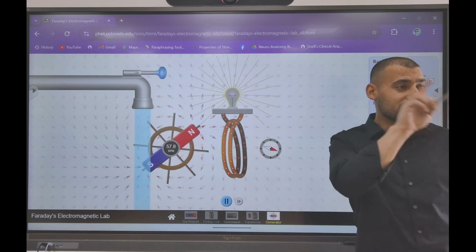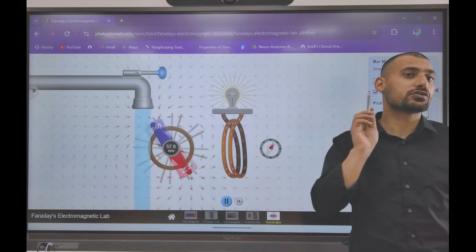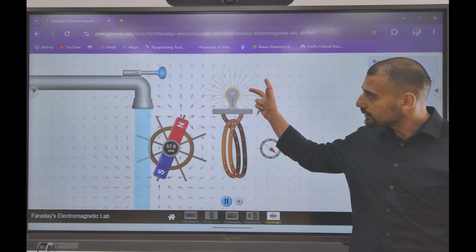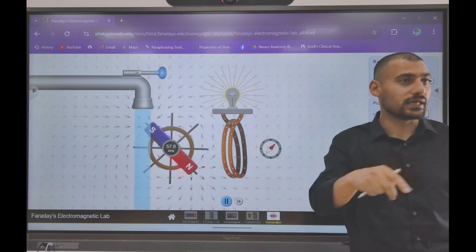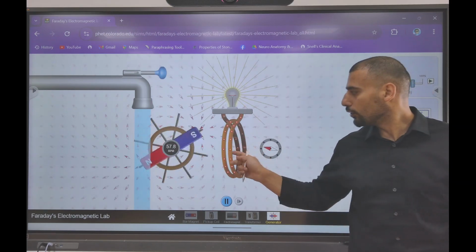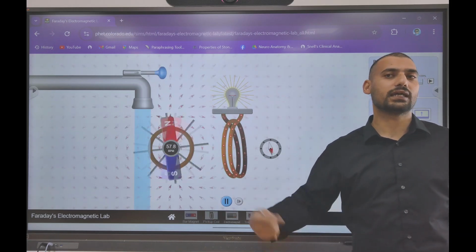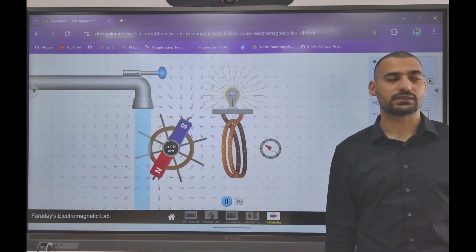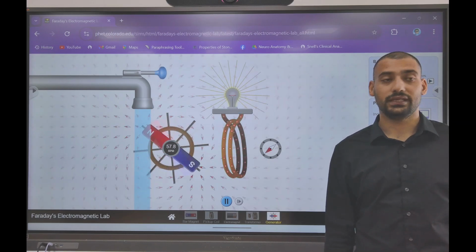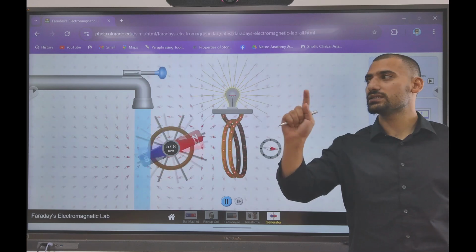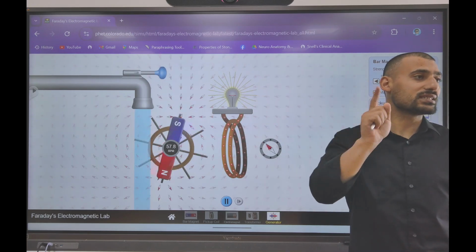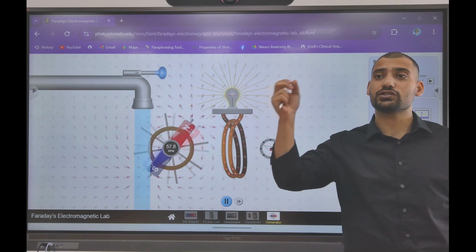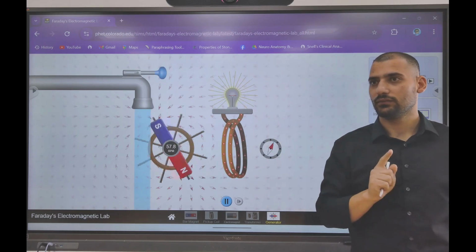And remember, in one cycle your bulb switches off 2 times. If you notice, it gets dim and bright, 2 times dim in one cycle. Depending on the frequency, we can calculate how many times it turns off in 1 second. In India, the frequency is 50, which means 50 cycles are completed in 1 second. In one cycle it switches off 2 times. Therefore, our bulb in India switches off 100 times in 1 second. But we are not able to notice it.